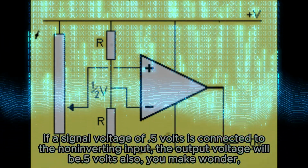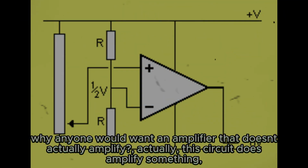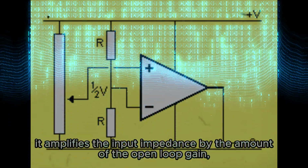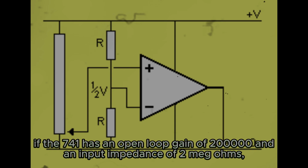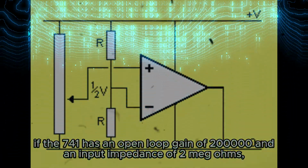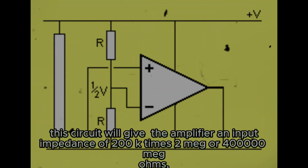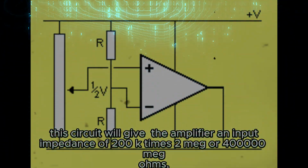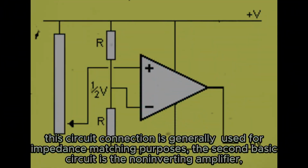You may wonder why anyone would want an amplifier that doesn't actually amplify. Actually, this circuit does amplify something. It amplifies the input impedance by the amount of the open loop gain. If the 741 has an open loop gain of 200,000 and an input impedance of 2 megohms, this circuit will give the amplifier an input impedance of 200k times 2 meg, or 400,000 megohms. This circuit connection is generally used for impedance matching purposes.